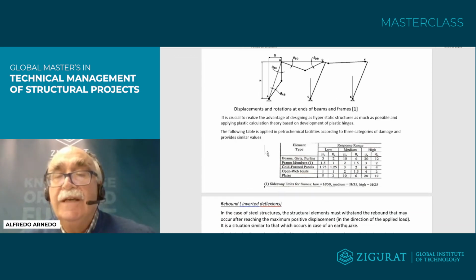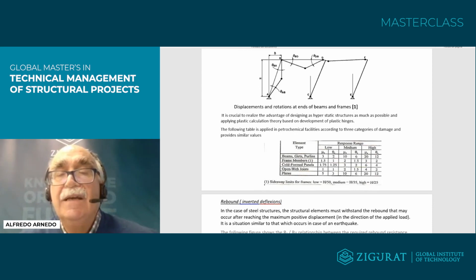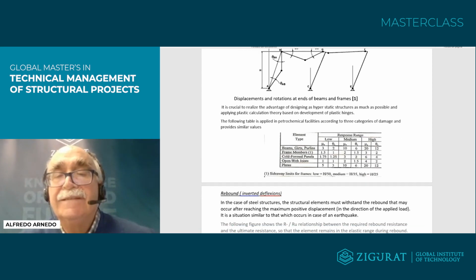So, to gain a good knowledge about plasticity, this process is similar to performing a pushover, a progressive calculation of the deformation, substituting this point by a plastic hinge and calculating step by step.